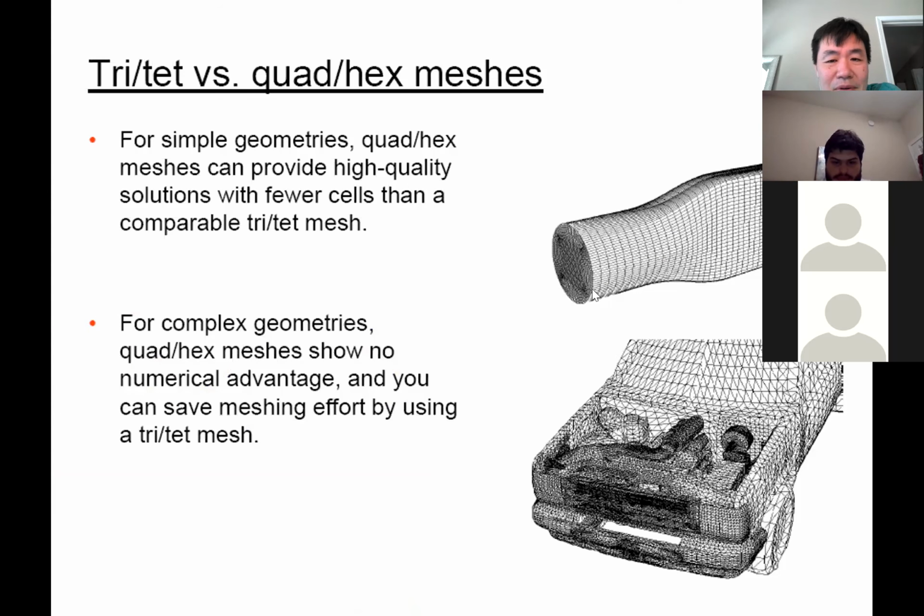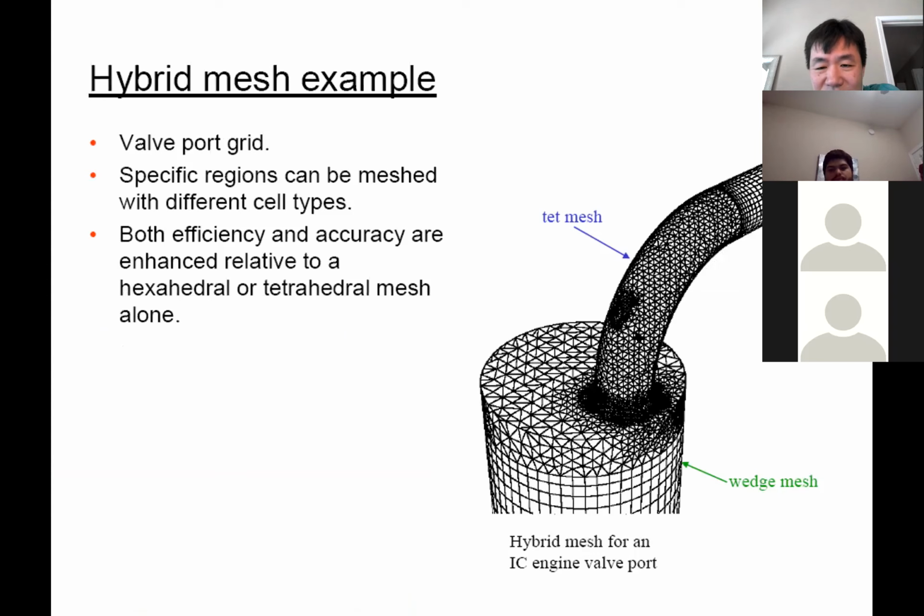Again, there are some other examples that use different sizes of grid to cover some space. Again, this is also an injection to the tank. It seems like it places very fine grid near the injection port. You know, the injection port where the flow enters the tank, it's very turbulent over there, the entrance port. It's very turbulent and very complicated. That's why you need a finer mesh to cover the region. It just shows the surface mesh, but it also reflects that the mesh inside the volume is also small like that.